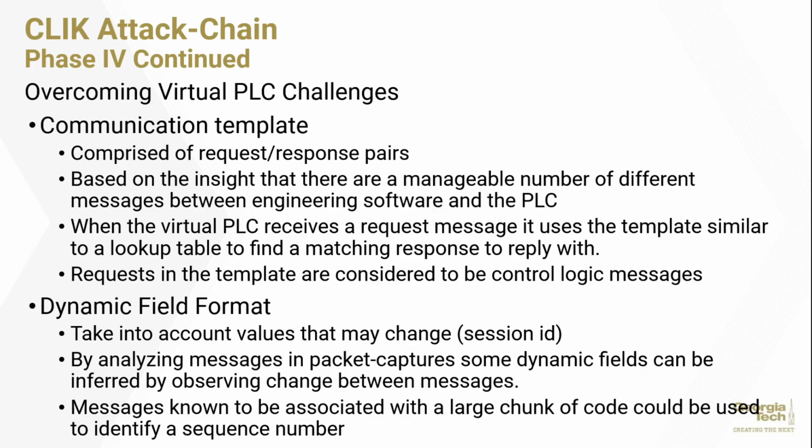And when the virtual PLC receives a request message, it uses this template, similar to a lookup table, to find a matching response and reply with that matching response. Any requests that are not on this template are considered to be control logic messages, which the virtual PLC can actually refer back to the original extracted PLC logic